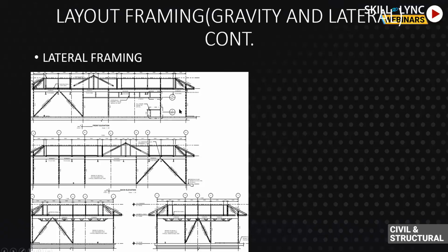So on this front elevation of the building, you want to have this K brace take up all the lateral load that is going to act on the building in this direction, maybe because of wind load, seismic load, or certain other lateral loads that can come in depending on the site and the local conditions there.